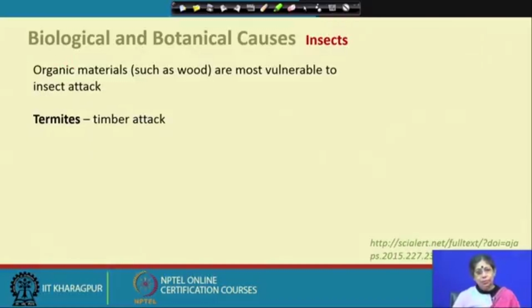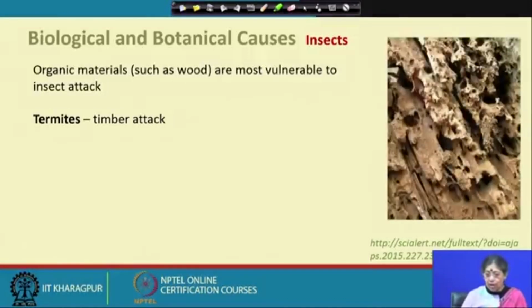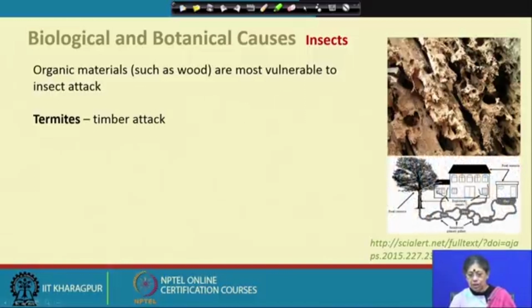The other very important thing, and which is quite damaging, is the termite attack. This is something quite dangerous, because sometimes we can't even know that something is happening. So, this is especially the wood effects. You can see that beneath the surface, termites can really deteriorate a historic wooden component, especially because they make a huge colony under the ground, and then they climb up.